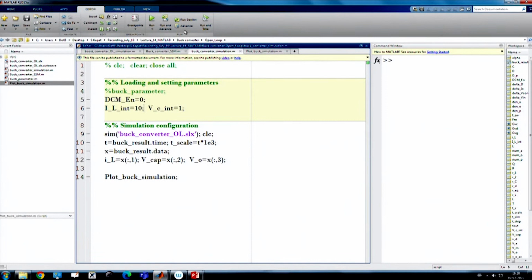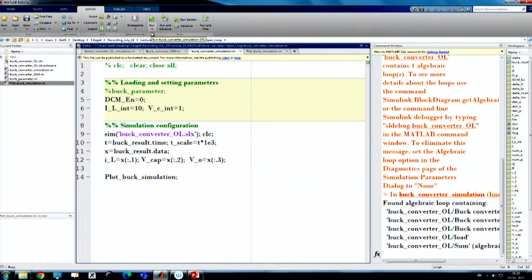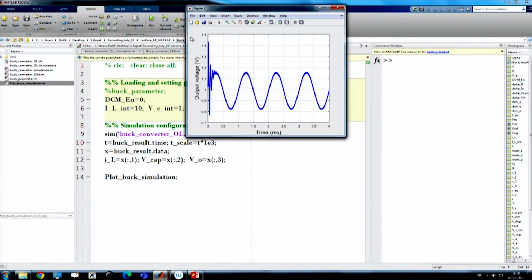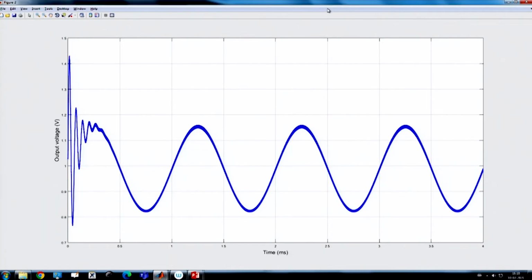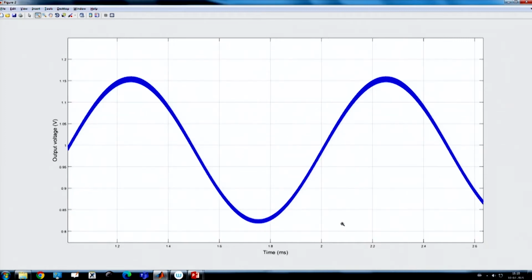So, earlier we considered a step transient and step change in the supply voltage, and we saw the effect. Now, we are applying sinusoidal excitation. The sinusoidal excitation clearly shows that we have applied a 1 kilohertz frequency of excitation, and that was applied on top of its steady state value. That means it has a DC voltage of 12 volt, and on top of that we have applied a sinusoidal excitation of 2 volt peak. That means peak to peak is 4 volt.